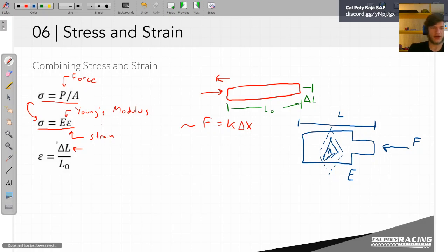So we said before, if we just solve this equation for this equation, we get U, our displacement. I'll call our displacement here U. Displacement equals PL over EA. Now, one interesting thing that you'll probably see with what I drew here is we actually have two different areas. So we have this larger section, and we also have the smaller section here. So we could have two different areas.